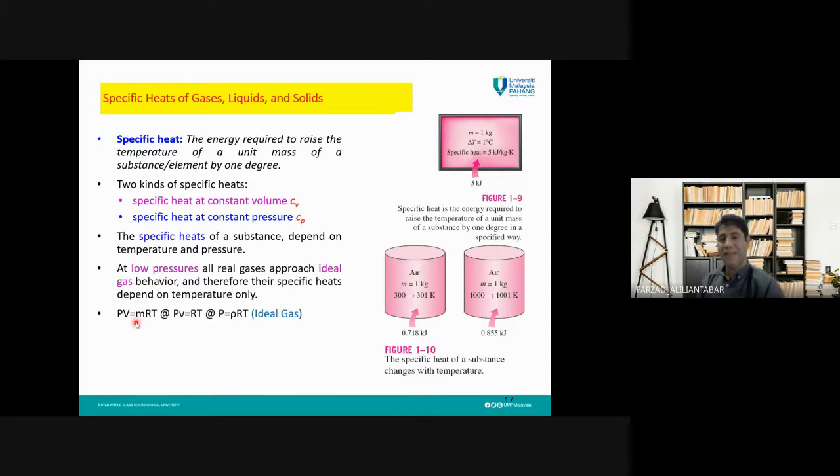And what is ideal gas? I'm not going to go into details of that. From thermodynamics, you can recall that. Ideal gases are gases for which we can write this equation. For most of the gases at low pressure, we can say that gas is an ideal gas. It is a little complicated to prove it. You need to know the temperature and pressure of the gas, then go to the thermodynamic table and compare with the critical temperature and pressure for that substance to be able to say if that gas is an ideal gas or not.